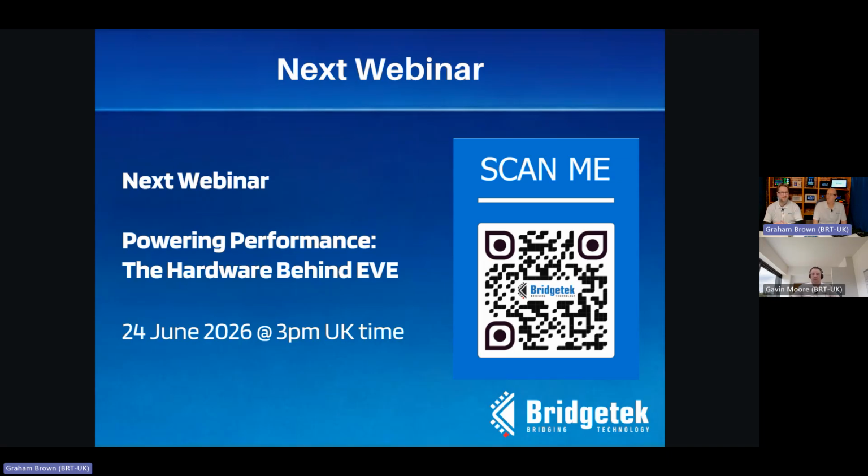You can send one list of SPI commands via your microcontroller to the EVE chip, and then EVE will continue to render this version of the screen continuously until you need to update the display with, for example, touch inputs, or a clock might change on the display, or something like that. And then you can get your MCU to reissue a new set of SPI transactions to the EVE chip, which will then update the contents on the screen.